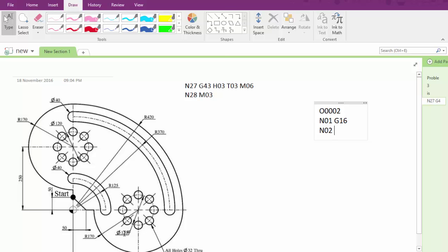This is phi 120 millimeter, so the r will be 60 millimeter. So the first hole, if we consider this hole number 1, 2, 3, 4, 5, 6, 7, 8 holes. So the first hole here will be at coordinates of r of 60 millimeter and theta of 0.